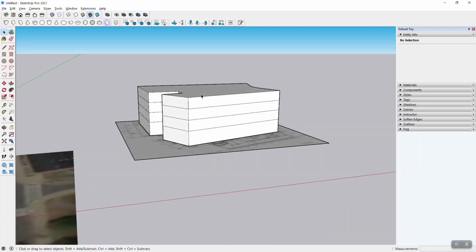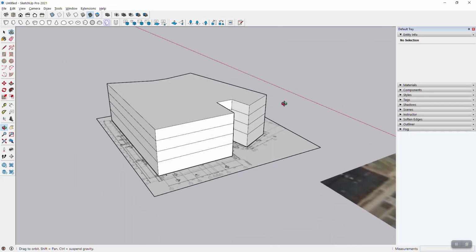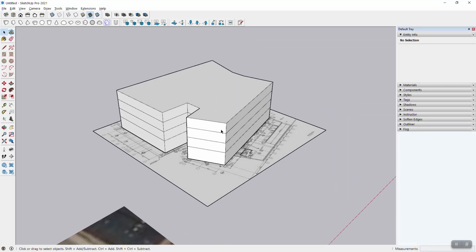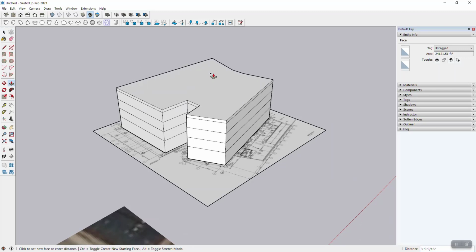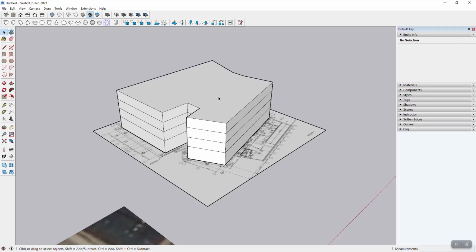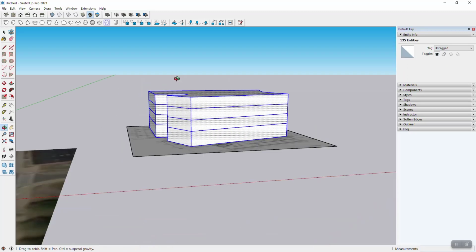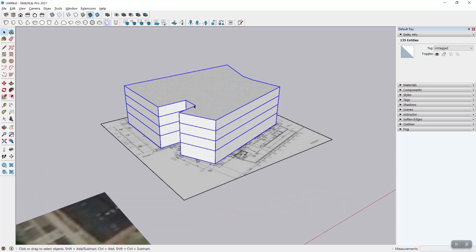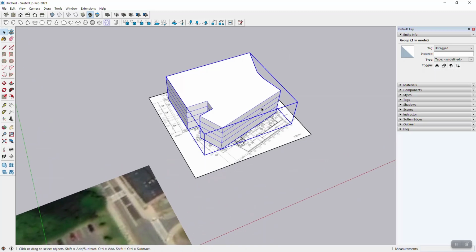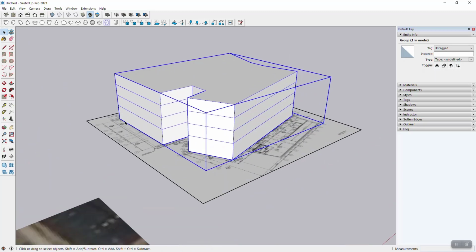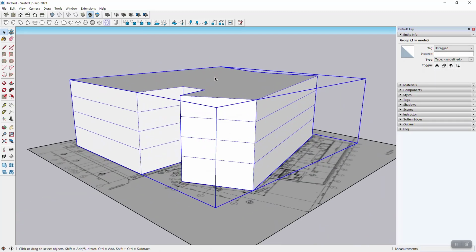All right, so now what I have is my extruded building shape, and I have these floors. And the floors, again, just came in because for the push-pull tool, I tapped copy so that I get that face. Now I'm going to triple-click this whole thing because I drew it on top of a group. It's completely separate, and I can right click and I can group this thing. And now I have myself a really nice rough building outline.